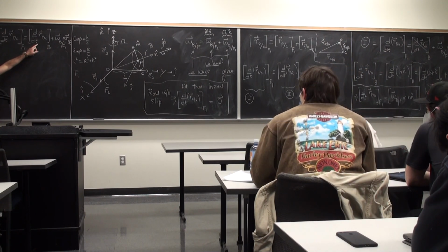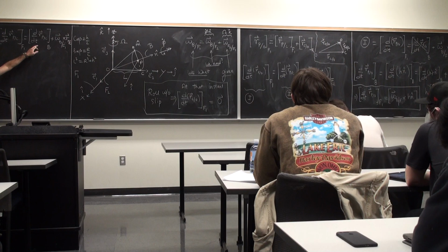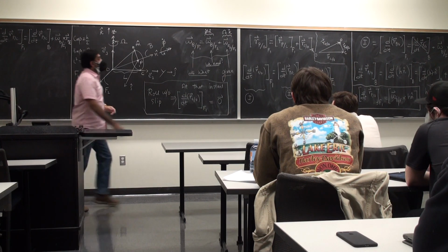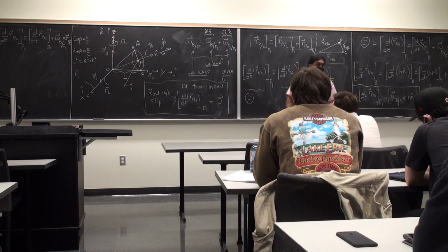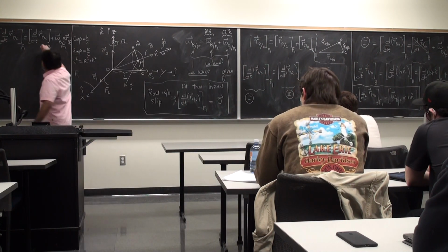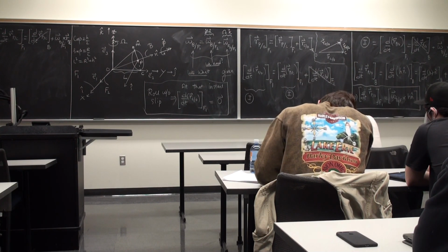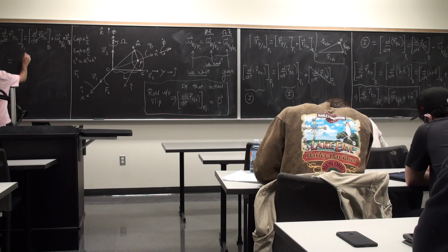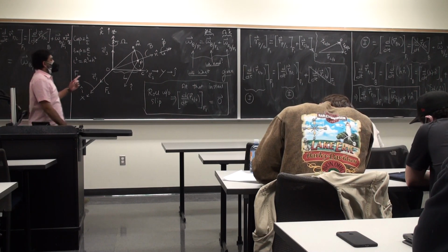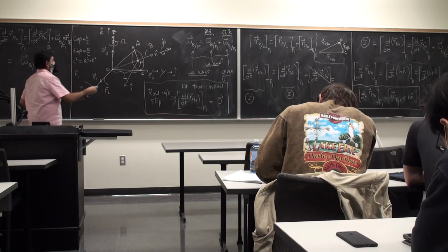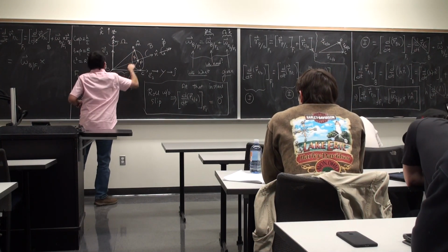This term here, can anybody tell me? P/c, I'm sitting on the body and looking at the rate of change of that term. Obviously that's going to be 0, or if you want, you can write it this way and then prove to yourself that it's 0. I'm not going to do that. That's 0. So term 2 leaves me with omega b/f1 cross p/c. Because I've used the body frame to write that out, I'm going to write this as a little capital R in the m hat direction.